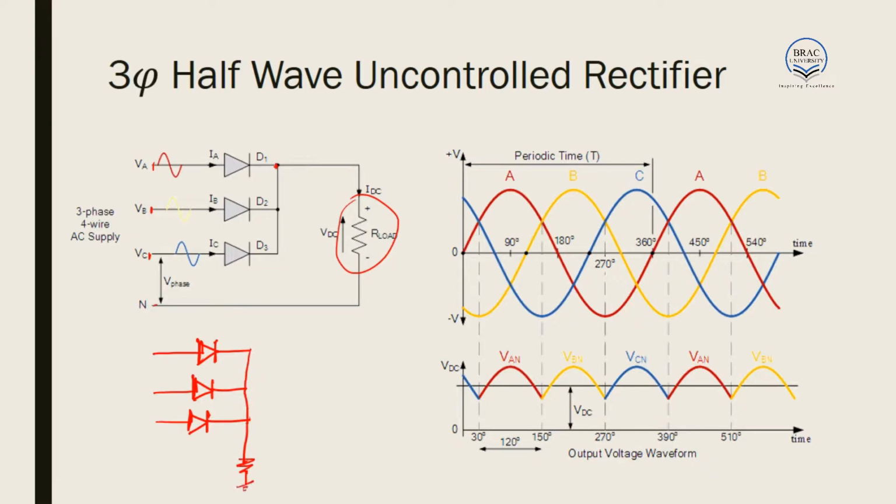and we have a load over here. Now, if there is plus 3 volts here, plus 2 volts here, and plus 1 volt here, what will be the output, V output? In this case, the output will be plus 3 volts. We are considering the diodes to be ideal. The output here will be plus 3 volts. That is, the maximum input will be mapped to the output.